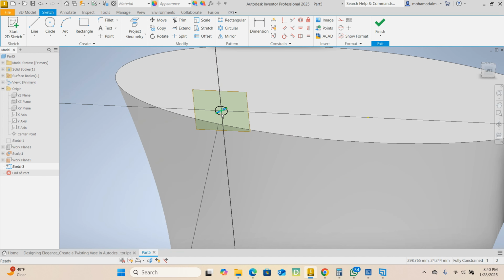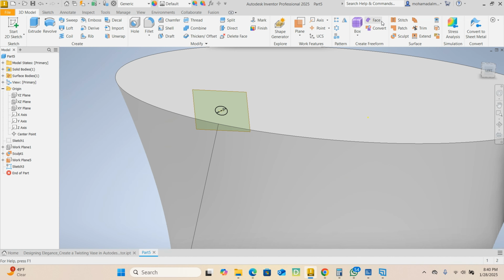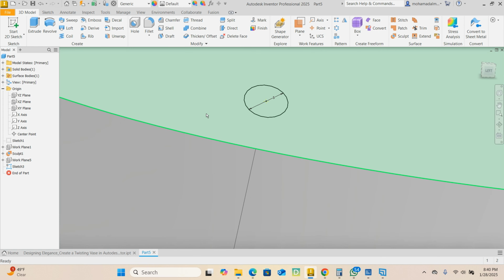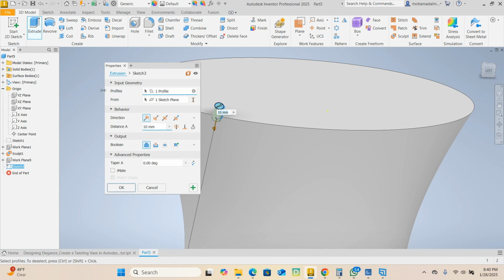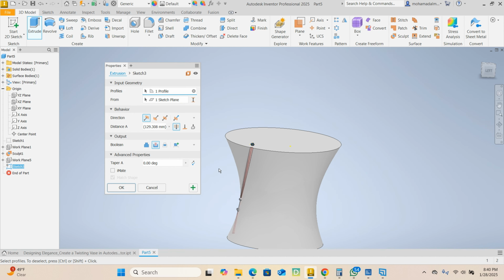Okay, now we've finished this sketch, and we're going to go ahead and turn off this plane and extrude. Let's cut it through, and make sure we are on cut. My direction is default, my output is cut, and I also have the distance as through all. Alright, and go ahead and select OK.